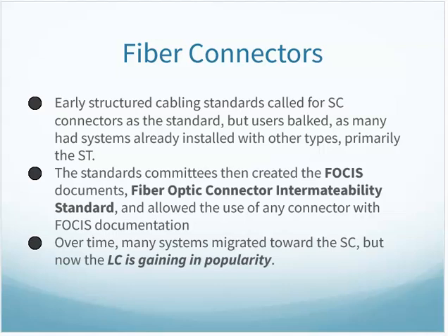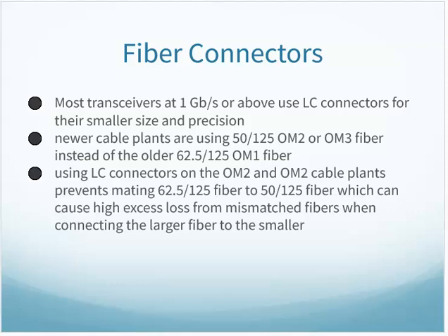If you look at the history, early fiber connections used ST fiber connectors, and then along came manufacturers who were like, hey, we can come up with something better. So the standards organization said, okay, as long as the signal moving through the connector is of this quality or better, so it did not have too much loss. Again, think about putting a connection on the end of a water hose. If you do a connection on the end of a water hose nice and tight, there's no water leakage. The same kind of idea with a fiber connector. If we have a good quality connector on there, light won't try to leak out. So the standards organization said, hey, as long as it meets this criteria or better, you can use different styles. Well, over time, different styles came along and they started creating different connector styles.